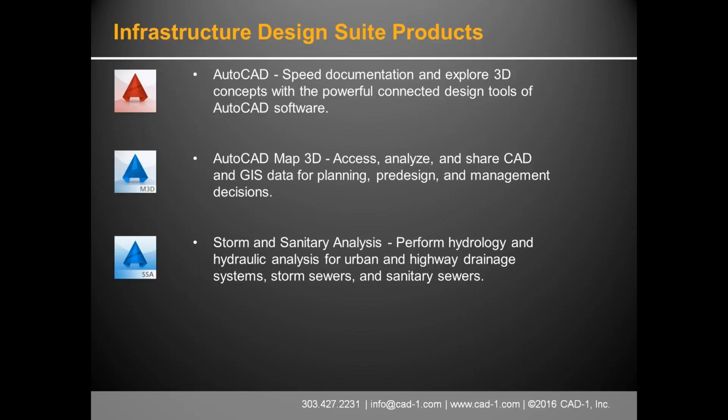Civil 3D also has all the HydroFlow things, the HydroFlow Express, HydroFlow Storm Sewers, and HydroFlow Hydrographs. But this one actually comes with, you don't need Civil 3D to get access to the storm and sanitary analysis. It comes in the suite just by itself. The other H&H tools have to be run through Civil 3D. Now the nice thing about storm and sanitary analysis, it does a whole system analysis. A comparable product that's available out there would be the Haestad Method Civil Storm. So that would be a product that would be similar in scope for this product here.